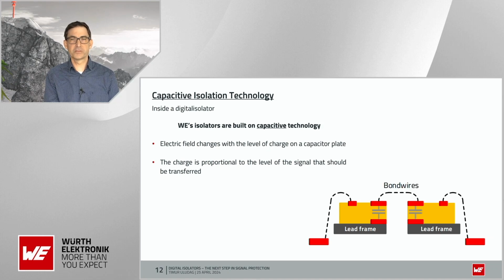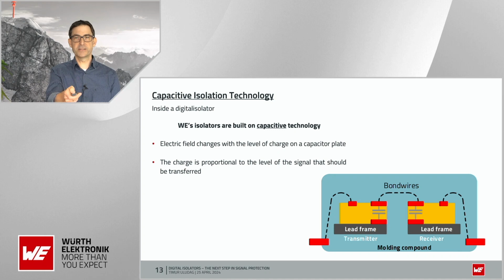Both capacitors are connected here via a bond wire, so that you have the first and the second capacitor in series. To protect the whole structure from the environment, we make a standard molding process and all is encapsulated and well protected. Now we know how it is built up.